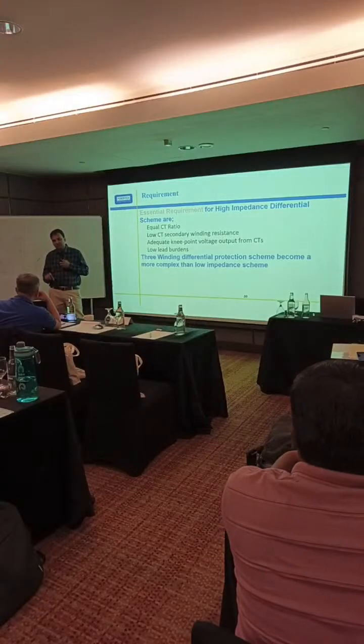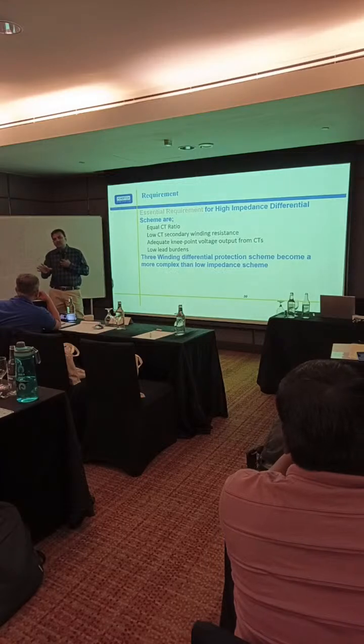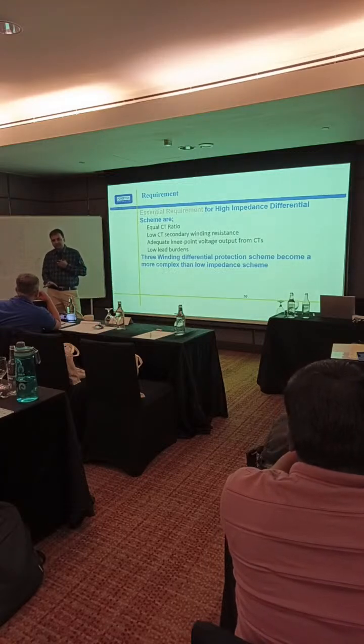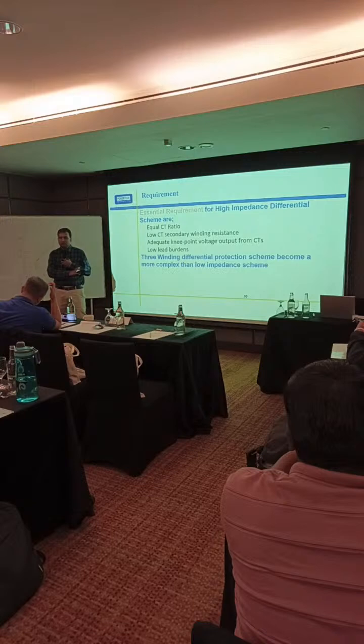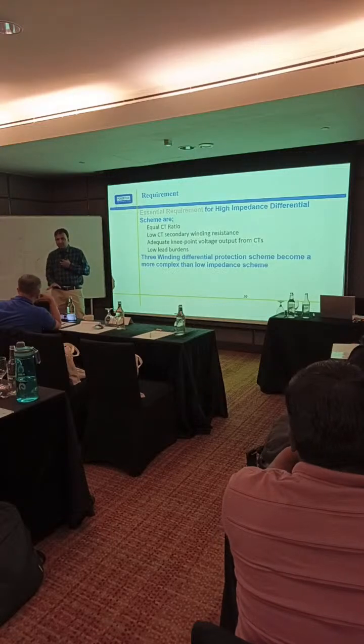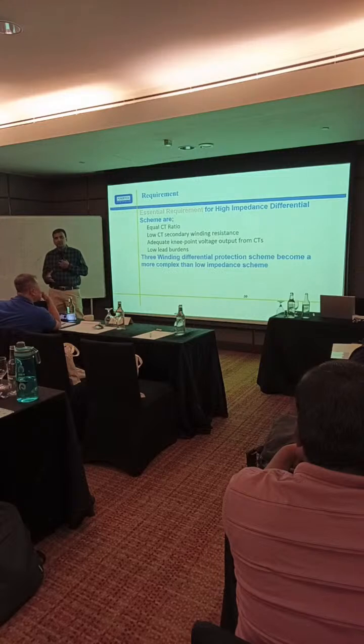Whatever relay you have, just go through the manual and you will find everything. They always recommend how much CT burden requirement, how much resistance you have to use, everything is in the manual.